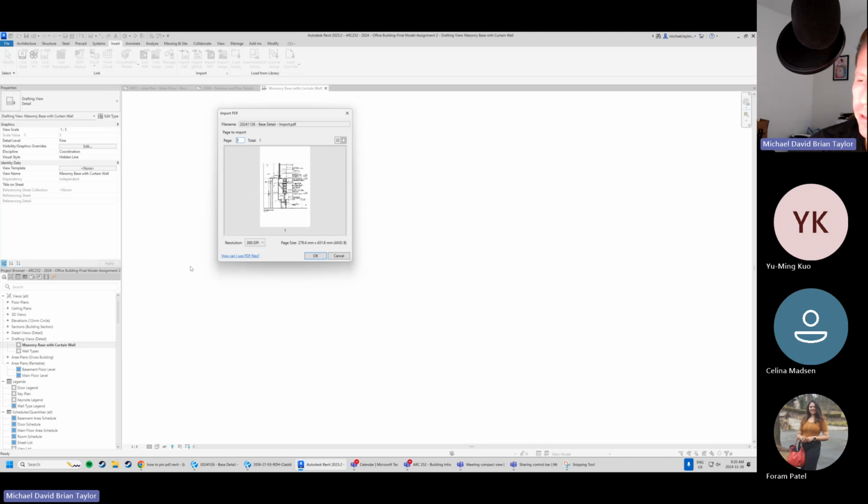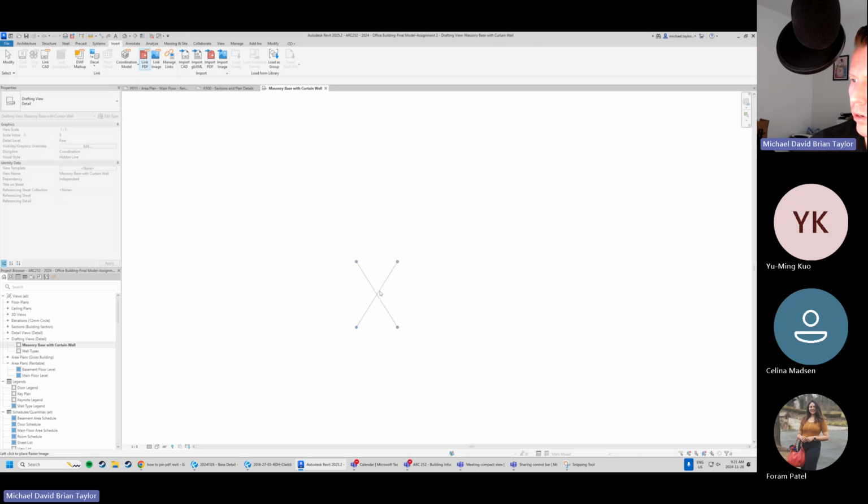And this can be an easy step to miss. So I'll give you an example of what you might miss here. We really want to set this resolution to a minimum of 300 DPI, dots per inch. But if I set it to 72, I'll just show you. Okay, here we've got a place prompt. So this is really asking how do I place my PDF?